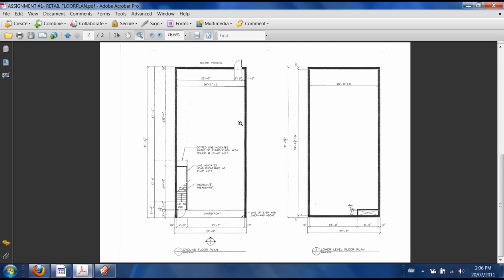Alright, so when I create these multiple floor plans, I like to first create them as separate floors that are all resting on the ground. Only once the design is completed, as well as all the furniture and all other aspects of that floor, at that time you might stack them on top of each other.